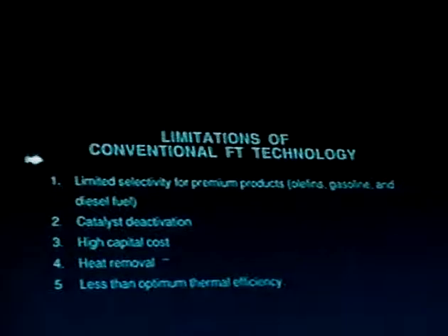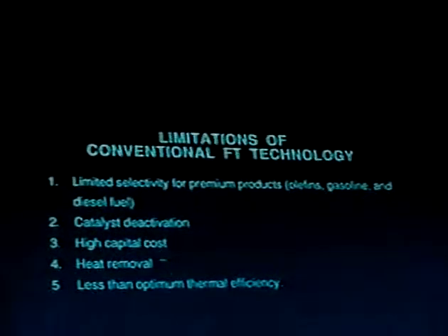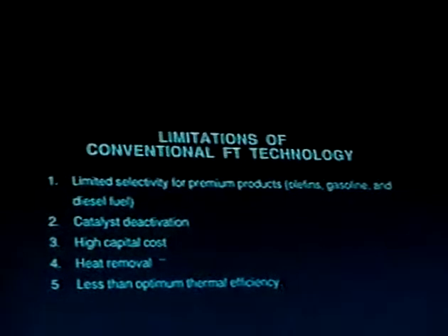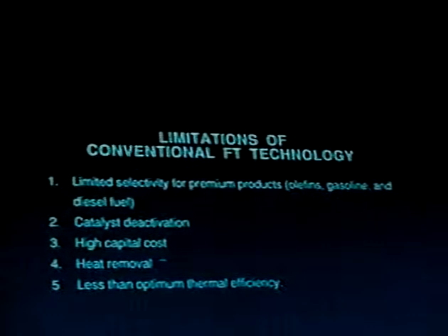Now, there have been a number of limitations historically in the Fischer-Tropsch process, and they include, foremost, the limited selectivity for premium products such as olefins, gasoline, and diesel fuel. But also, as mentioned in the previous talk, problems with catalyst deactivation, high capital costs, of course heat removal, and